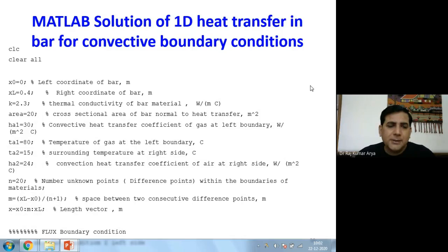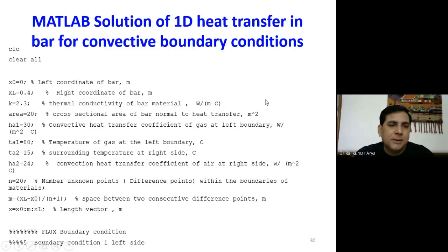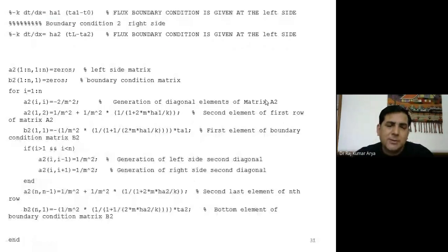So then you are just fixing your flux boundary conditions. I wrote here the flux boundary condition in terms of formula also, so that I should know whether whatever I am doing is correct or not. I was just talking in the program about this. You are maintaining conductive flux. You are maintaining a direction of flow, of heat from left to right, so the positive axis direction.